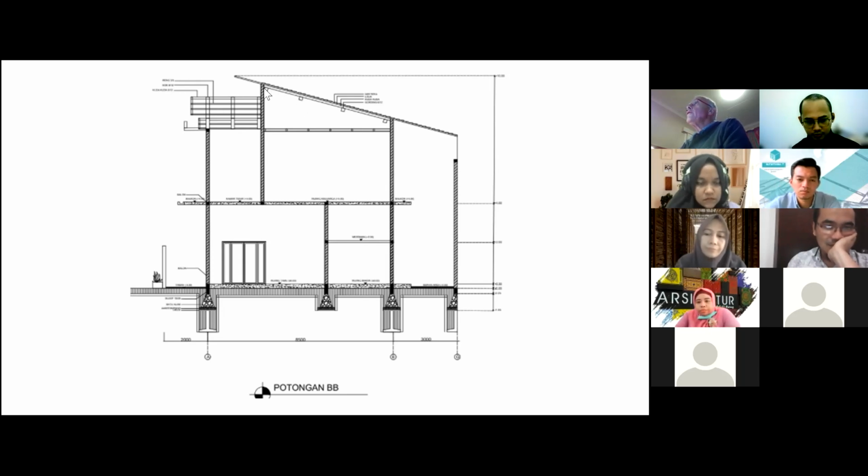And so then the loads go down the walls or maybe columns. And so now let's begin to talk about lantai dua, this floor here. And first of all, we notice that here we've got a very high wall and there's no beam supporting it. So there must be quite a big beam here to support this wall.